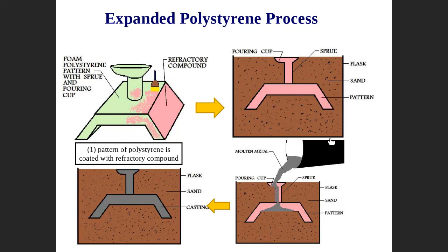And then you start, no need to take the pattern out. Previously, you put a pattern in the sand and we take the pattern out. Here, no need to take the pattern out. Just drop liquid metal on the pattern. The liquid here is very hot and the evaporation temperature of this kind of foam is very low.